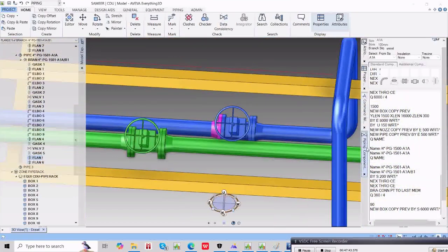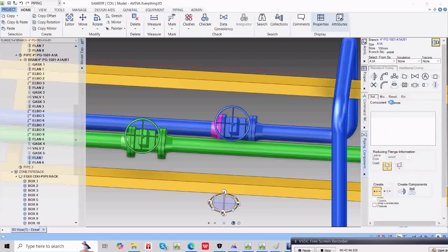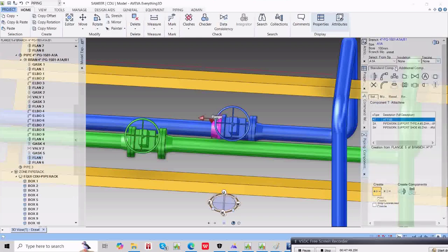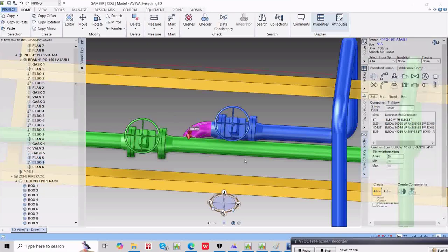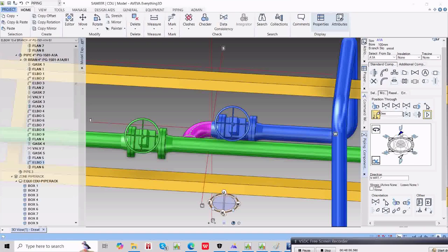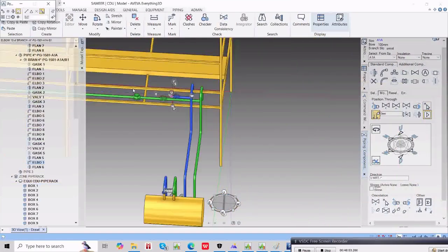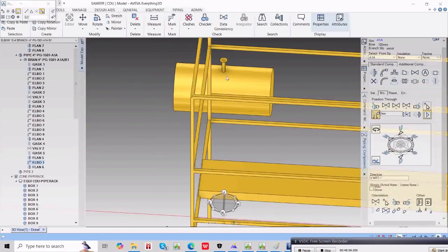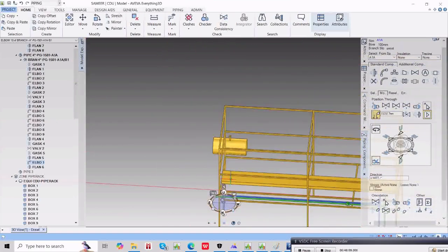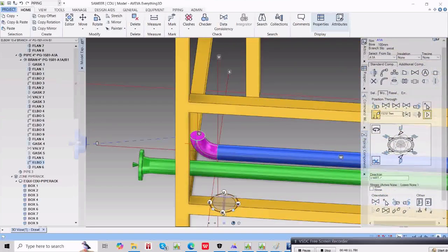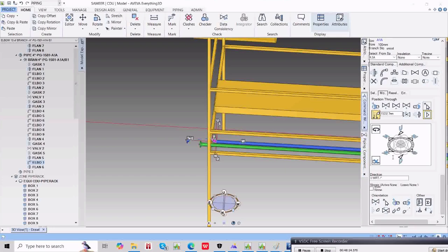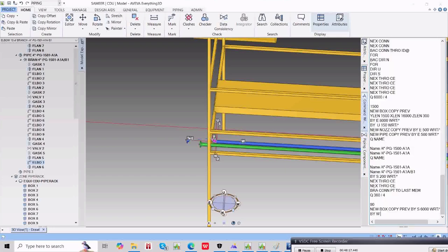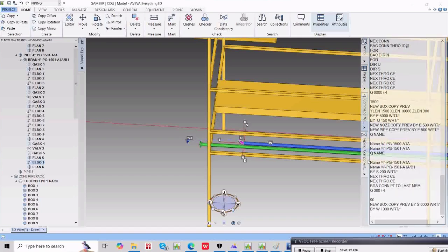So after this flange, I am going to create how to go outside right now. Okay, so I am going to create an elbow. Elbow 90-degree, creating elbow. Now the direction of this one is up. Now through ID cursor, I'm just going to click on this particular elbow. But this elbow is coming exactly here, so I'm not going exactly at the edge of the member. So by west, let us say 1 meter, WRT slash star, and then I am going to create one more elbow.